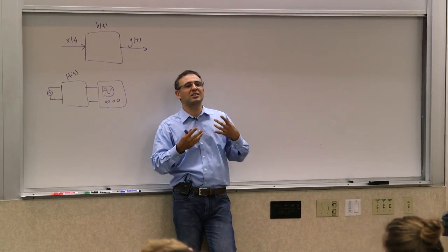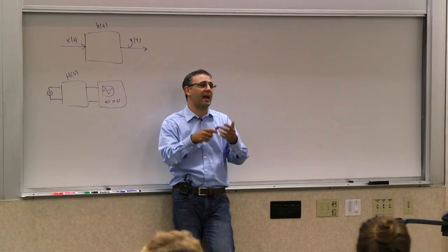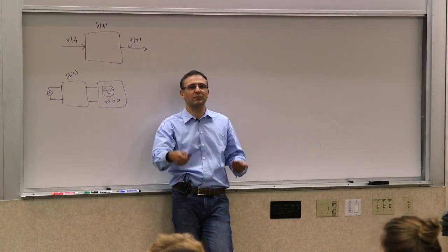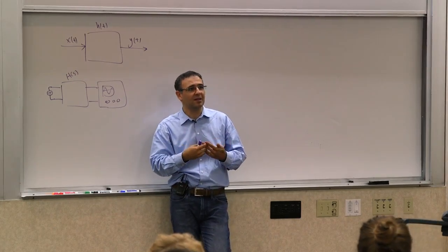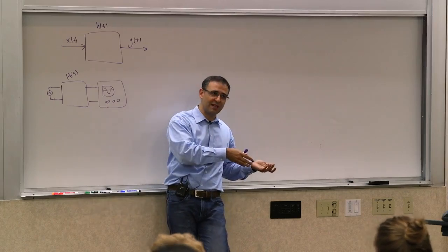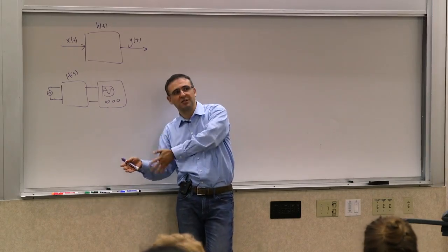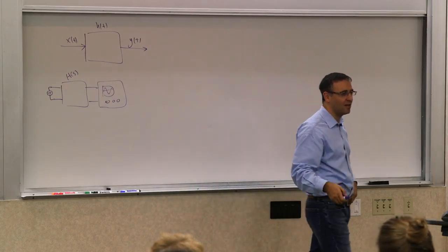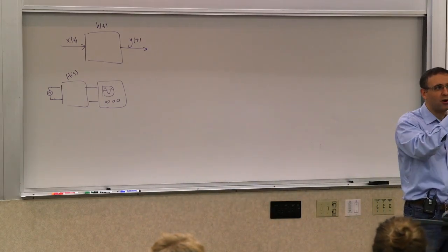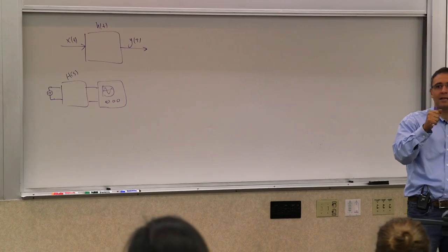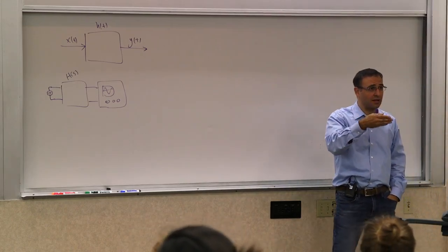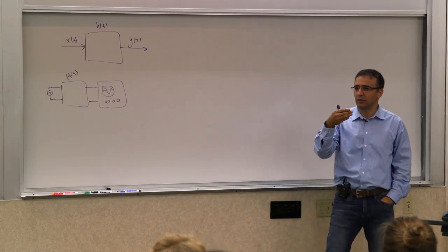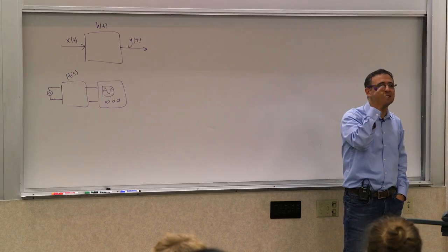So you can have a surrogate for an impulse even. You can have a step. Because if it's a linear system, the impulse is the derivative of the step, so the impulse response is the derivative of the step response. So you could do that. But again, it's a derivative. Now, you can do it, and it's done frequently, but there's something even simpler than that.